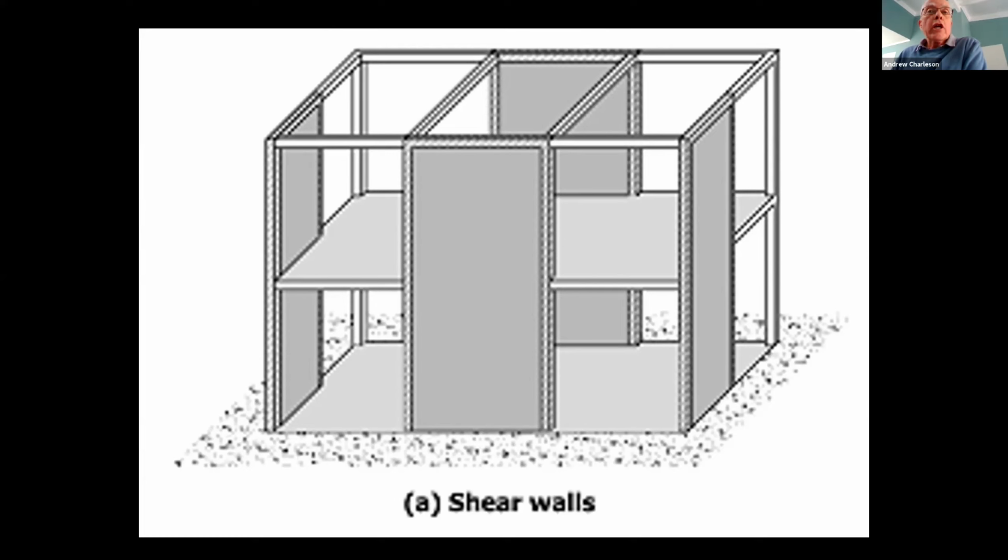And in Indonesia, for your many houses and low-rise buildings, you might use what we call confined masonry walls to resist earthquake forces, just for low-rise construction. But in your current project, which is between 5 and 10 stories, if you use shear walls, you would definitely use reinforced concrete shear walls.